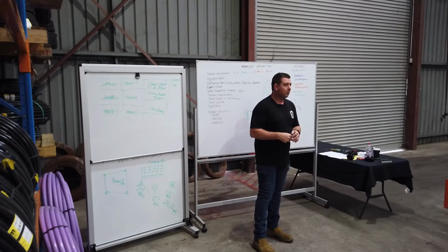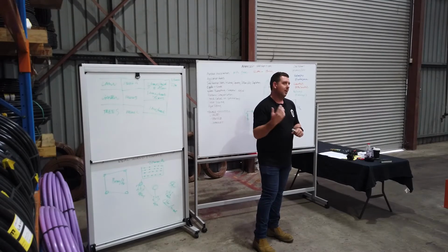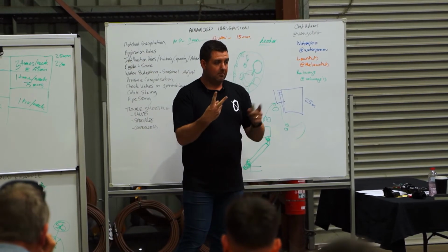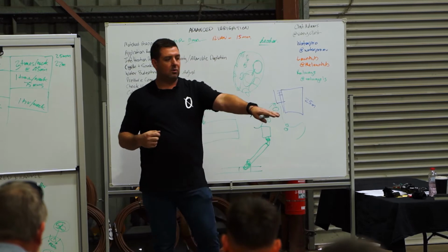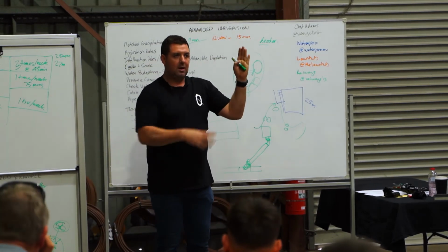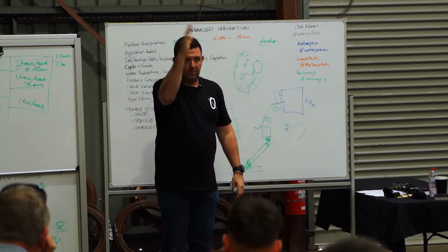So the best way to explain it for someone that's never heard it before is it's a 2-wire solenoid system instead of a multi-core solenoid system. So the way multi-core systems work is it sends 24 volt alternating current through a common and an active. The active is the color cable. So you've got brown, red, orange, pink, blue, and so on.